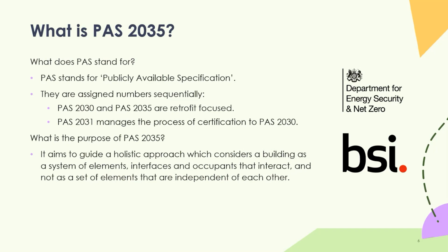So there are various other standards apart from PAS 2035. PAS 2030 is the standard for installers of retrofit measures on PAS 2035 projects. It's part of PAS 2035 compliance that the installers of the retrofit measures must be certified to PAS 2030, or MCS if it's for the installation of a low carbon technology. So that does cover heat pumps, but PV installations and the like as well. It does include, I think, battery storage now as well.